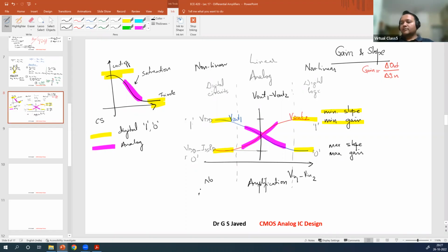Here, no amplification. Okay, but they will go rail to rail in the opposite direction. Here you will either get strong values, either closer to VDD or closer to ground. But if you observe here, the 0 that I am defining here is still closer to VDD. It is dependent on what is ISS over RD. So now you can define the output depending upon the value that you prepare. And for that, this line is going to be beneficial in the analysis.